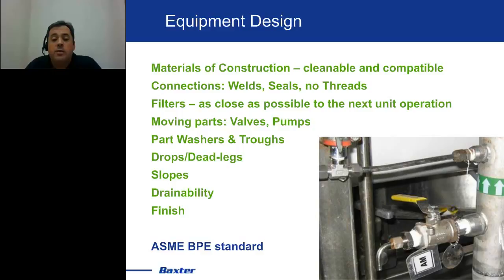Filtration is certainly a useful component. However, filtration only is effective at preventing issues upstream of the filter. Anything after the filter can't be controlled by that filter, so it's usually good to place it really close to your next unit operation. You need to think about your moving parts. Valves and pumps, things like that can break down over time and create areas for microbial proliferation and retention.